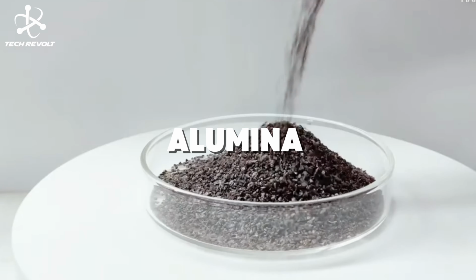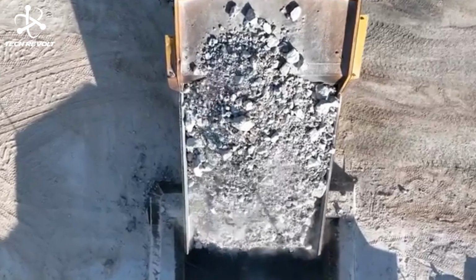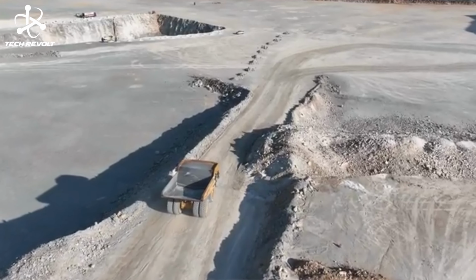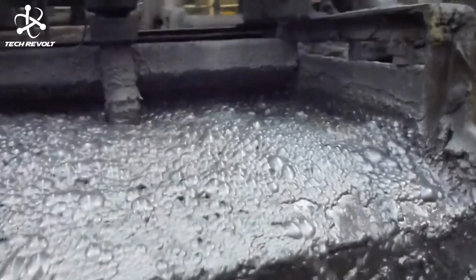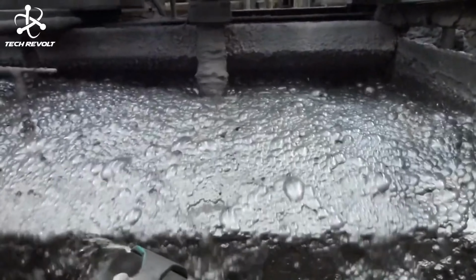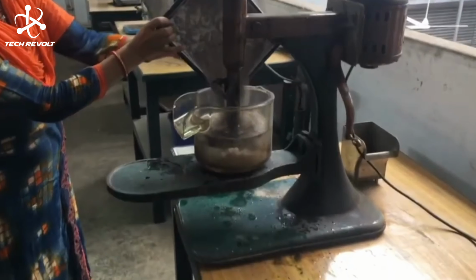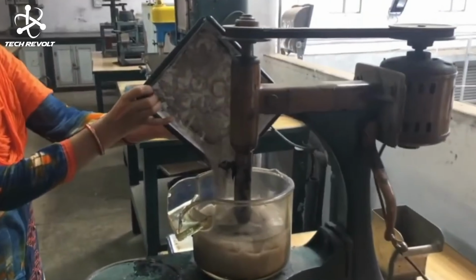and alumina. In regions where limestones of sufficiently high lime content aren't available, some process of beneficiation can be used. Froth flotation will remove excess silica or alumina and upgrade the limestone, though this is a costly process and is used only when unavoidable.